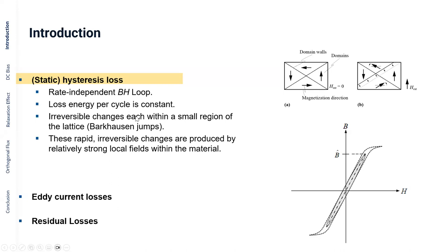Very generally, you can say that there are three kinds of core losses in magnetic materials. One is the so-called hysteresis losses. What are hysteresis losses? If you magnetize a magnetic material, which can be well represented by a BH curve, even if you do this magnetizing very slowly, ramping up and down, almost infinitesimally slowly, you will still have a certain area of this loop, and this area represents core losses in the end. Why is this the case?